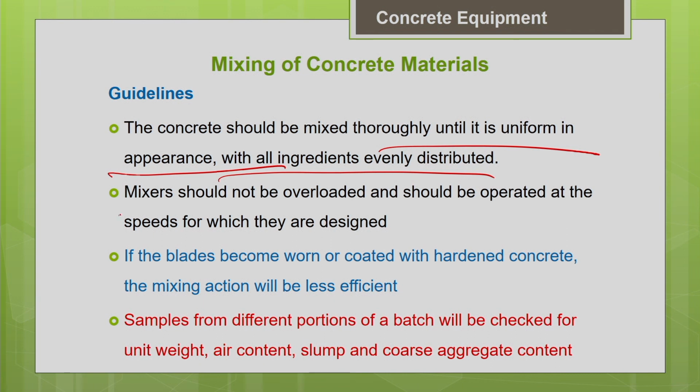Mixer should be never overloaded. If you overload it, the mixing won't be homogeneous, and it should be operated at the speed for which they are designed. As I told you, free fall mixers are designed for a particular speed. Power mixers are designed for a particular speed. You should go as prescribed by the manufacturer.